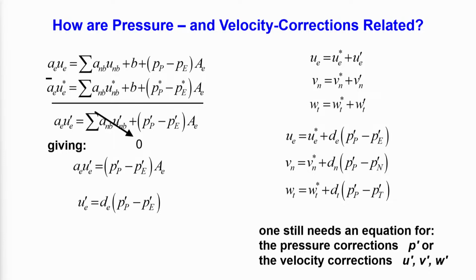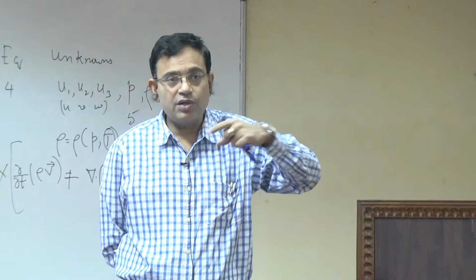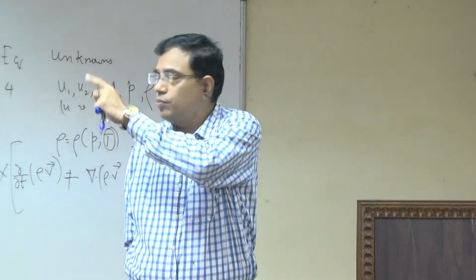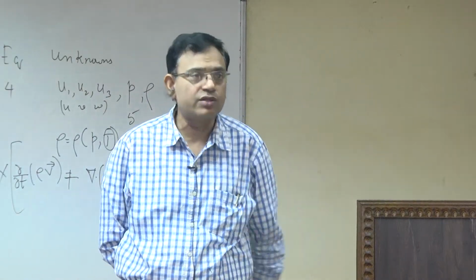So, what this algorithm tries to do is to simplify the calculation, it drops the neighboring term. Then you can argue that suddenly it is dropping, so it is wrong. What you have to recognize is that it is just a way of getting into convergence. If you did not drop it, it might lead to a technically more correct way of getting into convergence, but once it is converged by some way or the other, the correction has no meaning because it has converged to the correct value. So, the correction is 0. Whether you drop it or not will matter in terms of how you reach convergence, but once you have reached convergence that is not going to matter. So, omitting that is not going to make any fundamental error in the final solution.